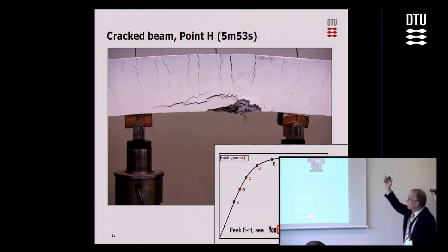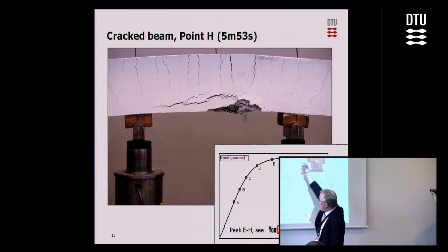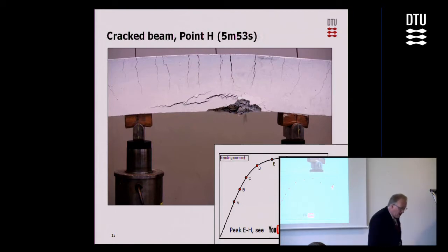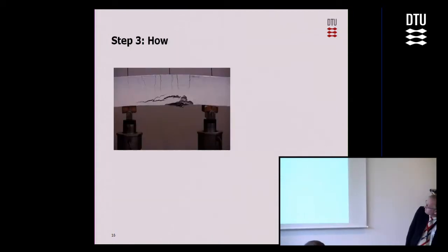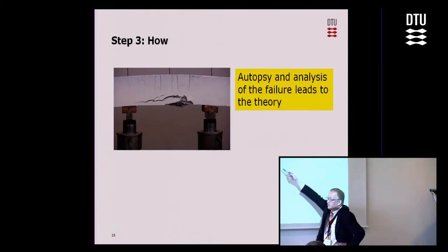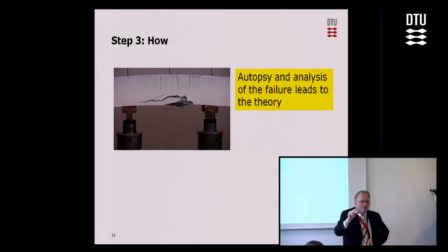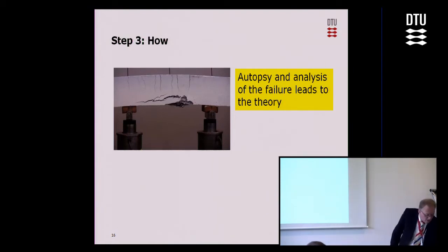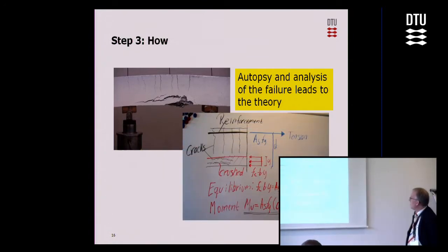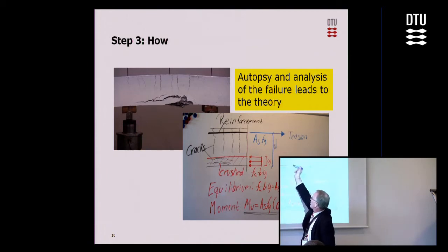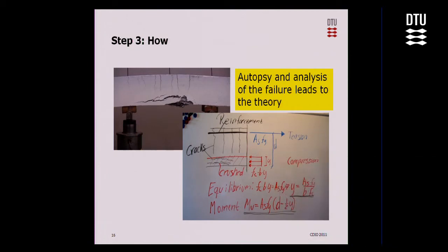And I would normally leave this picture up on the screen. I would make a simple drawing of the crack patterns. And you might say, we would then be doing an autopsy of the failure based on our common sense, based on what we see. And then we can argue, well, if we have such large cracks up here, we probably can't transfer any force in this direction except in this steel bar that's up here.